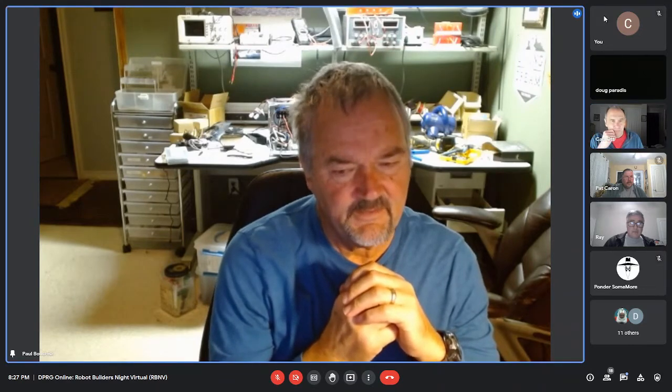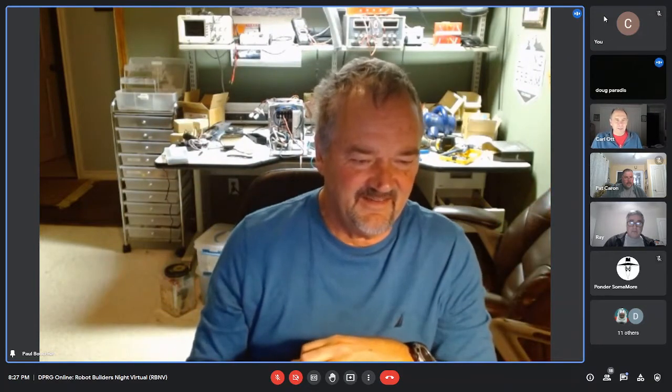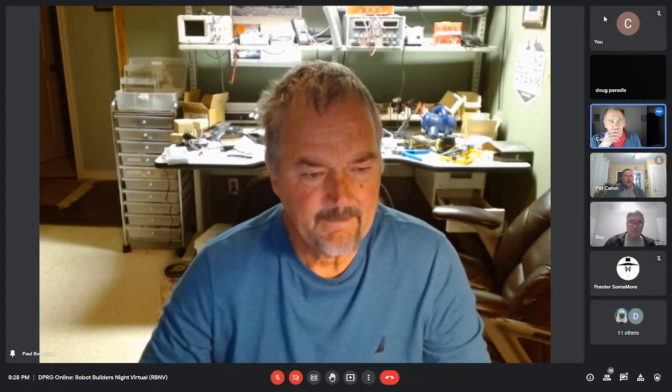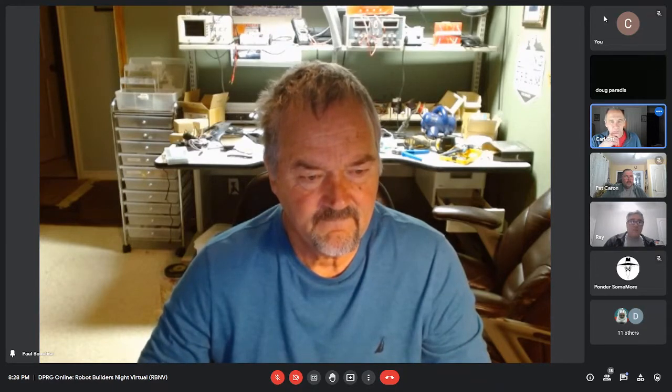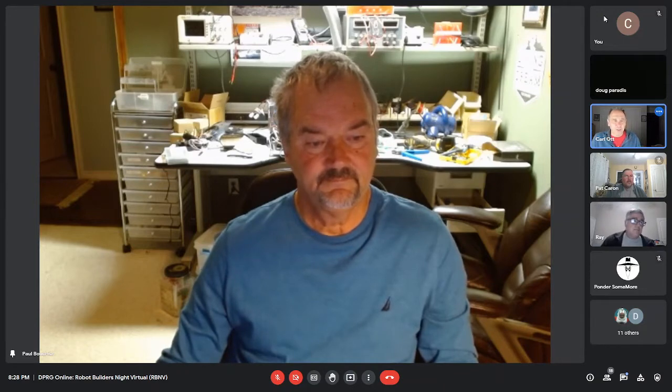Okay. Thanks for the advice. Yeah, I'll do that. And yeah, I use an electric drill just like someone said. Yeah, it's easy. But I don't know enough about this specific bus, I2C, but at some point, if you had too much capacitance, then you won't get clean edges and it won't work. So you can have too much shielding in that way, because a coax cable would probably at some frequency give you a lot of capacitance. So it's a trade-off.